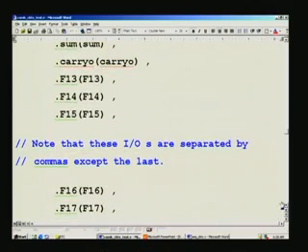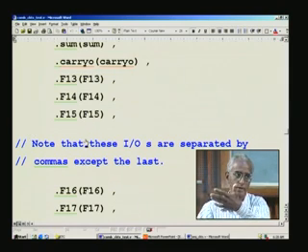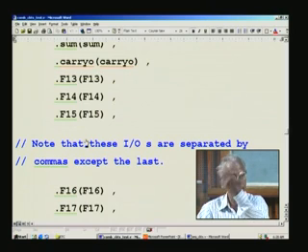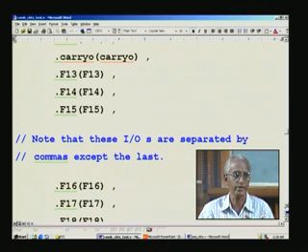In the bracket you can give different names. Yeah, with a different name, it need not be the same name, right. This pertains to the present one, right. I can give it as F25, so long as that is declared as a wire here in this particular level, whether it is a test bench or even in the design module, which we will see when we deal with bigger design applications.